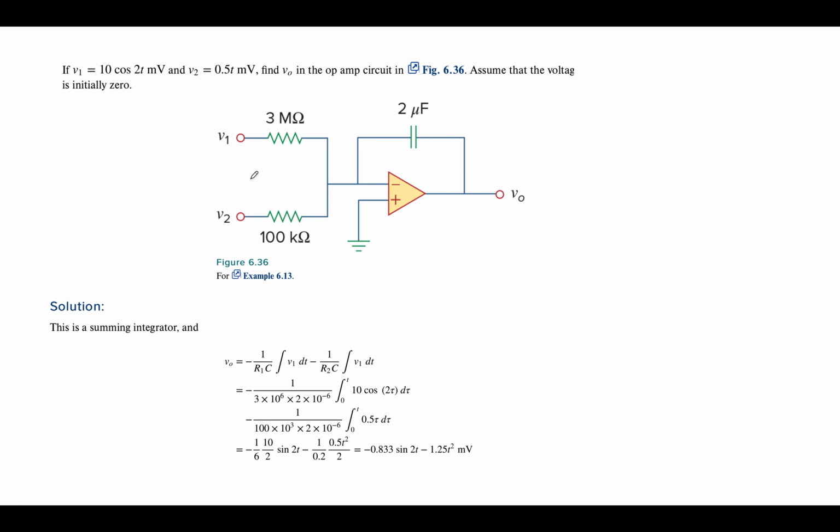Alright, I wanted to show this one because I think it's super cool, and we're going to do another project with op amps where we use an op amp as an analog computer. So we have our op amp, and first let's look in the feedback loop, and you notice we don't have a resistor, we have a capacitor. So that means we've constructed an integrator.